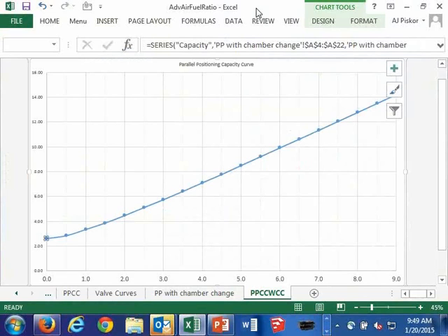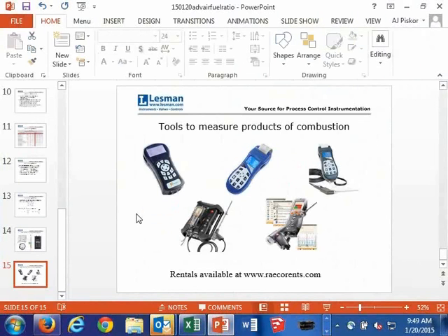Adjusting the burner while monitoring flame temperature or burner refractory temperature is a decent method of achieving maximum heat. However, what's a good way to measure maximum heat transfer from the burner? For example, increasing excess air might cool the flame, at the same time increasing the heat exchange rate within the process. Is there a tool to measure true maximum flame energy, including heat transfer rate?